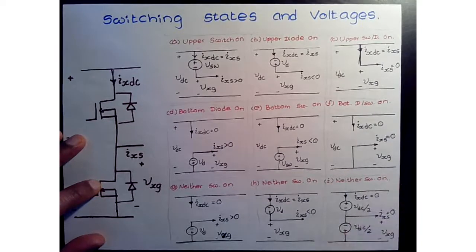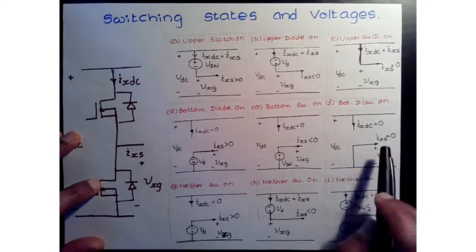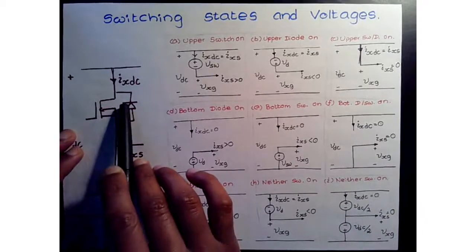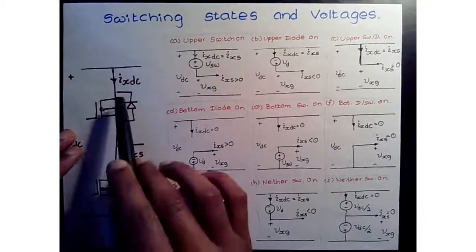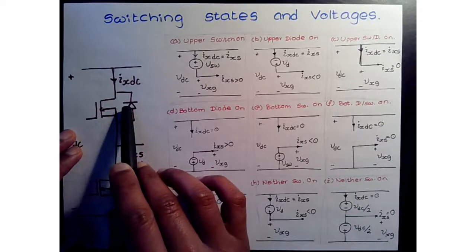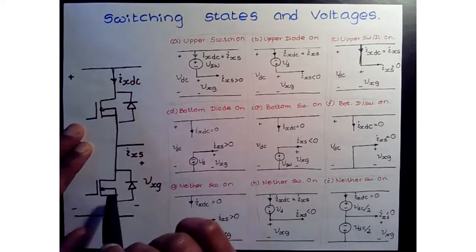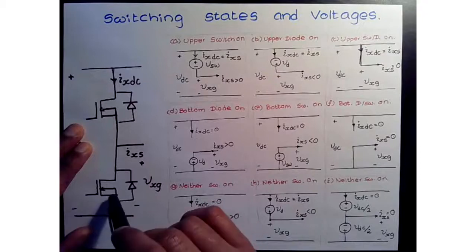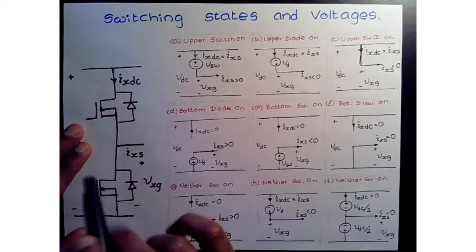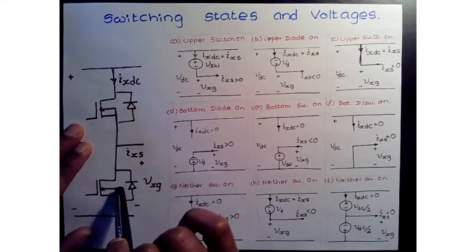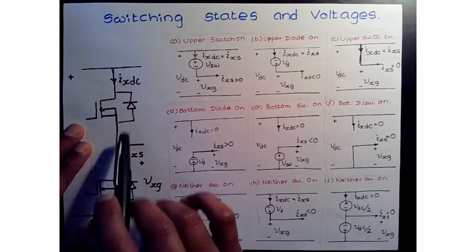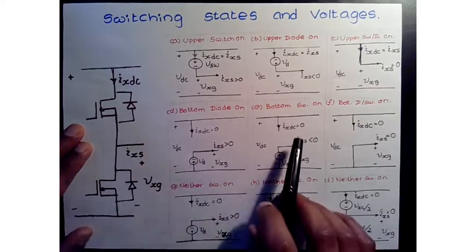Okay. Now we do need to keep in mind there's a concept called dead time when you turn the top switch. So it's a sequence, right? Whether this is on or this is off. When one switch turns on, let's say the top switch turns on, and the period before the bottom switch was on. So when you do that, you want to have enough time between the turn-ons of the individual devices so that there is no interval that both switches are on at the same time. Okay, that way you can prevent shoot-through, and that's called dead time.